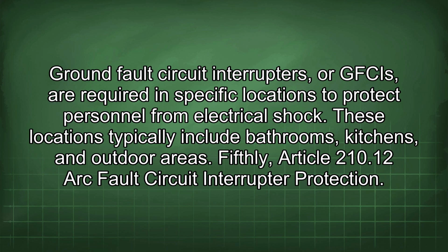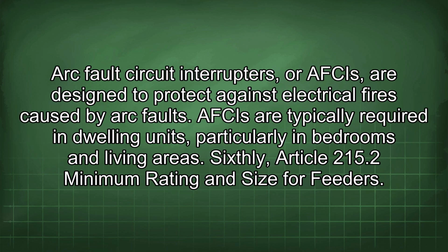Fifthly, Article 210.12 Arc Fault Circuit Interrupter Protection. Arc fault circuit interrupters, or AFCIs, are designed to protect against electrical fires caused by arc faults. AFCIs are typically required in dwelling units, particularly in bedrooms and living areas.